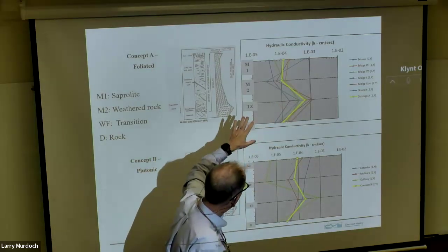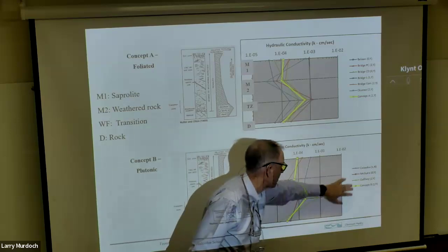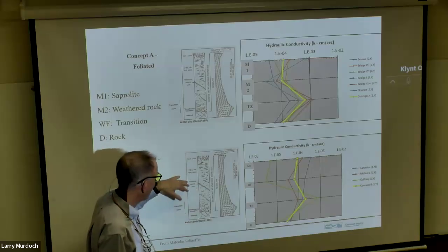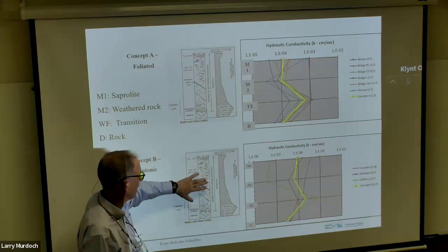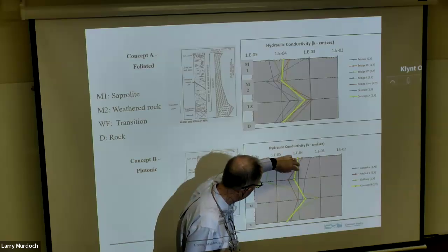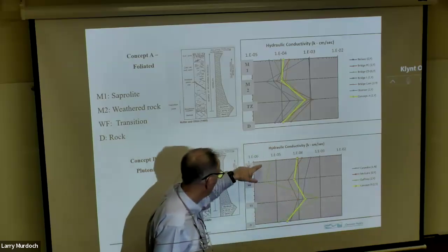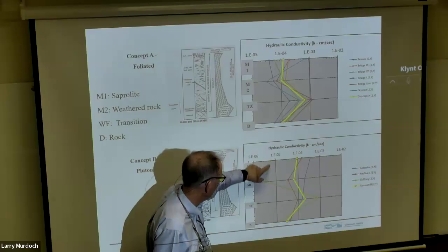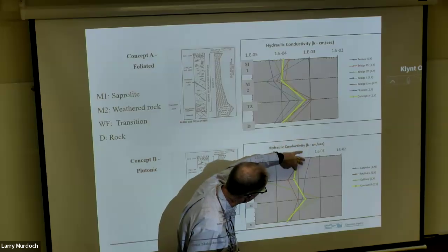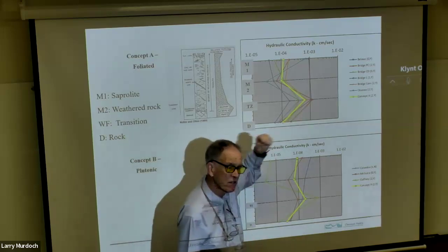Okay, in this other one, these 4 sites here are underlain by more massive rock that doesn't have as strong a layering. And in this case, here's that same number, that 10 to the minus 4, and you can see it's bouncing around. Here's a site at Gaffney where at shallow depths it's really low permeability. But at these others, it's just kind of bouncing around this 10 to the minus 6, and we don't really see the same peak here in the transition zone.